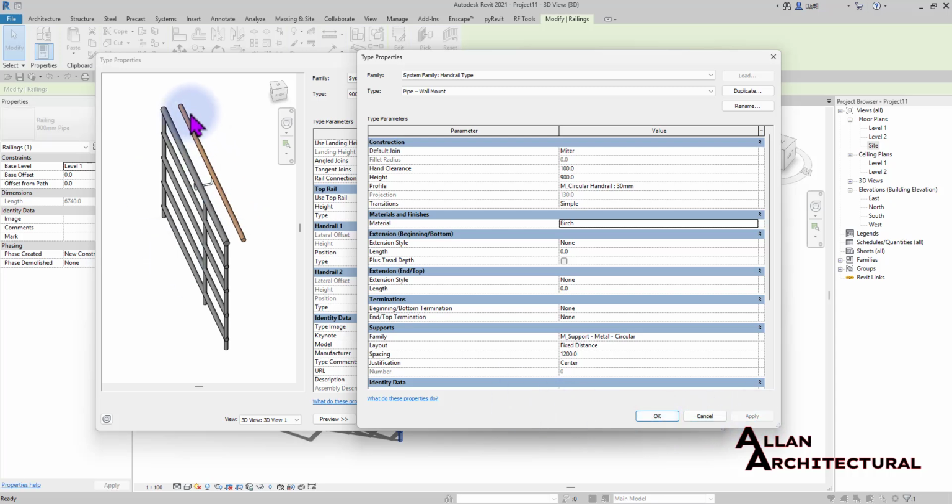Now you notice our railing has 100 mm spacing in between there, so we can decide to make that, let's just keep that at 900. Hit on apply, and this is fine. Oh, I think I did that with the height, so let's just keep the height at 900, and let's take this all the way to 800 in there.